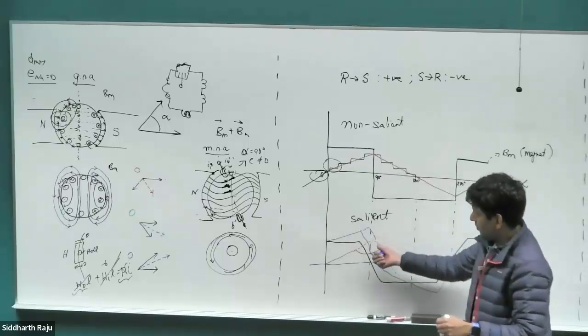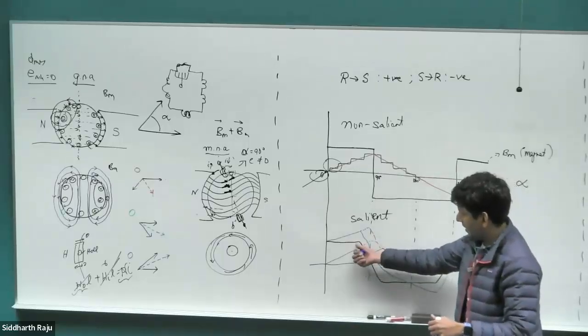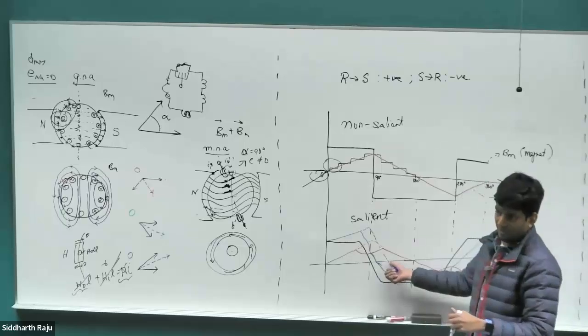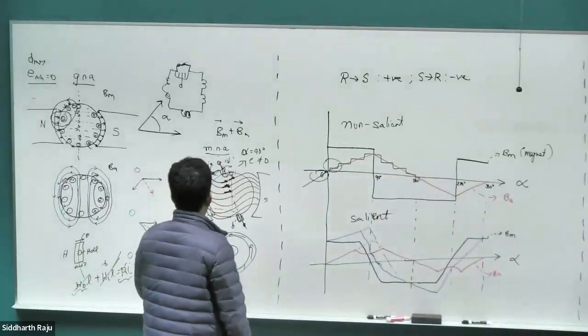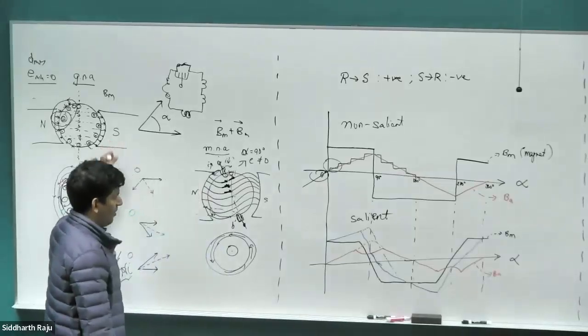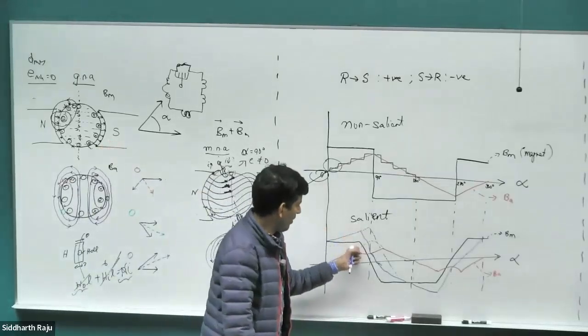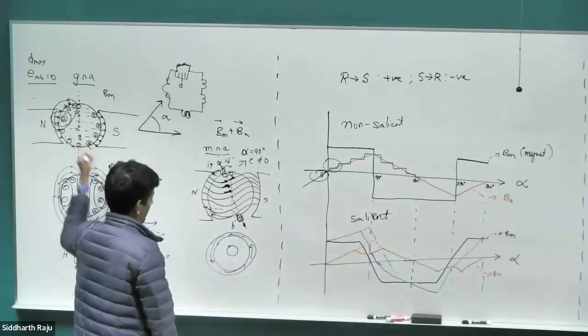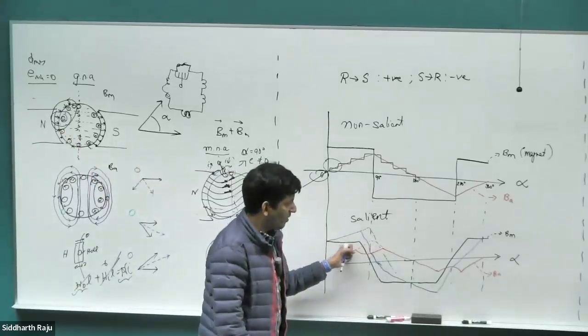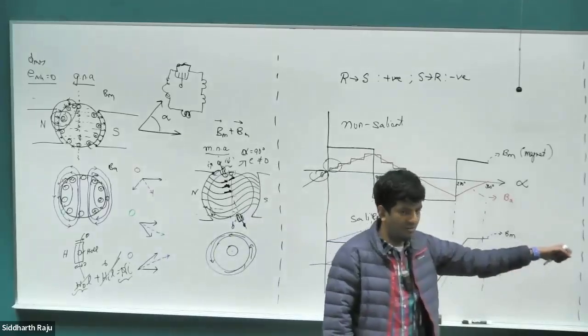This is what our net sum of the dotted red plus the black line would have pushed it way farther out. So our magnetic neutral axis would have been way farther out if we didn't have the saliency. But the minute we add that saliency, around that 90-degree point, the magnetic field due to the armature conductors starts to collapse because you have increased the Lg in the denominator, right?